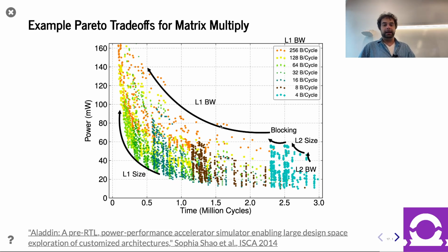So I don't have the numbers in front of me. You can follow this link on the paper to go read it, but I believe there was some validation of the model, and I think there was some amount of error, of course, but it was smaller than you might think. It turns out doing a full synthesis, place and route, and all that kind of stuff is overkill for early stage design exploration, right? The odds that a point here is going to jump over here if you do a full run maybe isn't that high. Maybe, not guaranteed technically, but so do the early run of like 500 points with that really fast modeling. And then when you get down to your most promising 30 points, you start doing the full place and route.